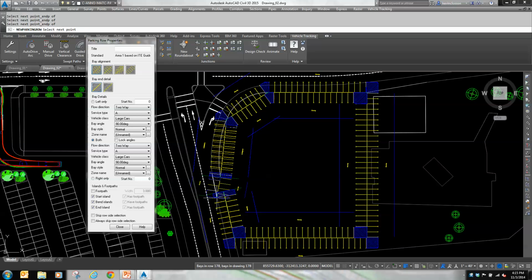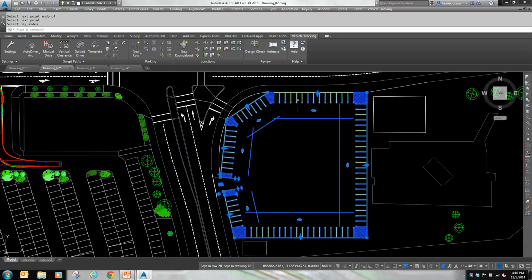Now, with limited time, you'll notice, I'll right-click here, I'm hovering above and below that line. So if I want this on both sides, I just would hover somewhere toward the middle, and you'll see that there's arrows on both sides. In this case, that'd be a problem because we'd be striping in the middle of our road, so I'm just going to keep it on the inside, and you see where the arrows are pointing in. And all I got to do is select that.